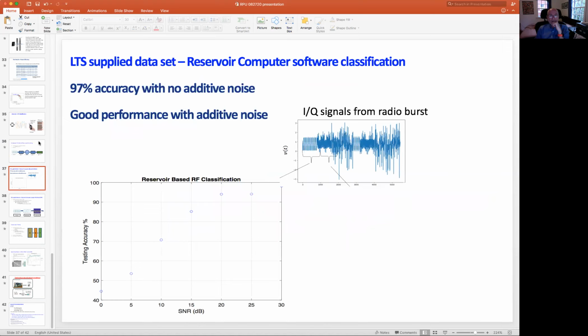So, in practice, what we did was actually take from these radio bursts just the very first part of the burst. An example burst is shown in the middle right here. There tends to be in all of these transmissions a preamble, a modulation sampling, and then a data packet. Those of you that can remember old-fashioned modems probably have heard similar things happening, where there would be a hum and then a chirp and then data coming through. Those of you that have not heard it are younger than some of the rest of us.